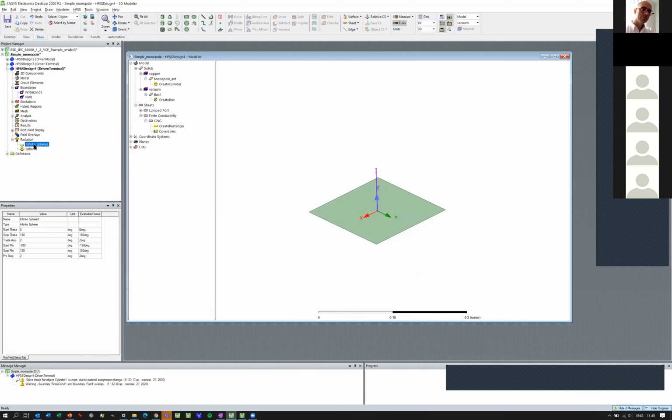Anyway, now I'm measuring the radiation really far away, ideally like 1 kilometer away or something. It's just measuring the infinity radiation pattern. This is giving us the near field radiation pattern. Well, we don't need this second one. It's typically not interesting, but the far field one is really interesting to do. Once again, I will save the project.